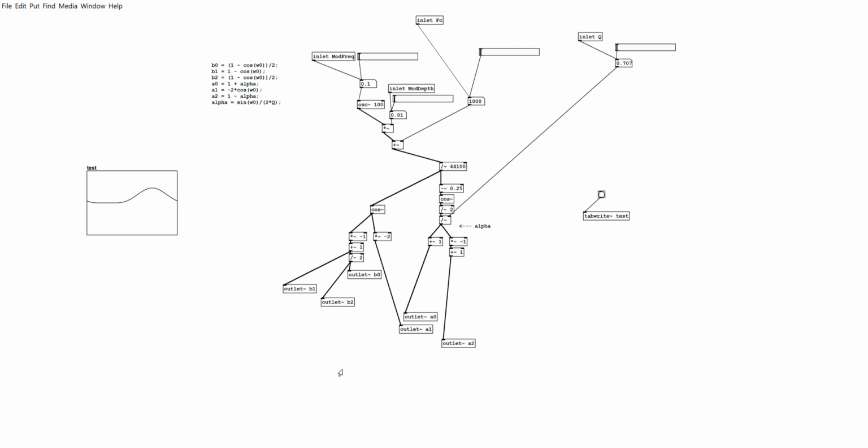And we'll talk in another video about how you actually use these coefficients to create a filter that varies over time. But needless to say, this is how you can take these simple quantities FC, Q, and modulate them, turn FC and Q into signals, and generate your 6 coefficients, all as a function of time. And again, you can use the AudioEQ Cookbook that will be linked to set up a slightly different version of this type of patch to create different filter shapes.